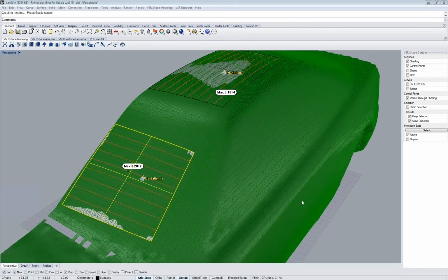The reason why we are using a different one is, if you're measuring G2 to a very flat surface or planar surface, it is very easy to get the maximum error while the surface transition is still good. So the light lines look great, but you still get a G2 error of 1. Trying to avoid that, you can have different mathematical definitions of G2, and you just want to have this kind of definition to make sure that if G2 is alright, then you've got good light lines, of course in this direction. But you also want to ensure the other direction. Well, if you always have a G2 error of 1 while the light lines are good, this is not a good definition of G2 then.